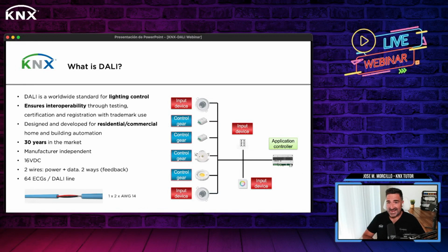And if you don't see anything in the market in KNX, no problem, because you can integrate into KNX with a Modbus gateway, BACnet gateway, or just a binary input module. So there's no need for the device to be pure KNX or native KNX, you can integrate it into KNX, and as long as it's in KNX, everything can work.